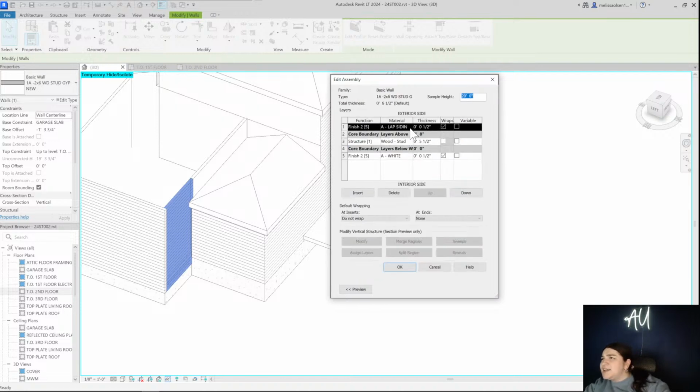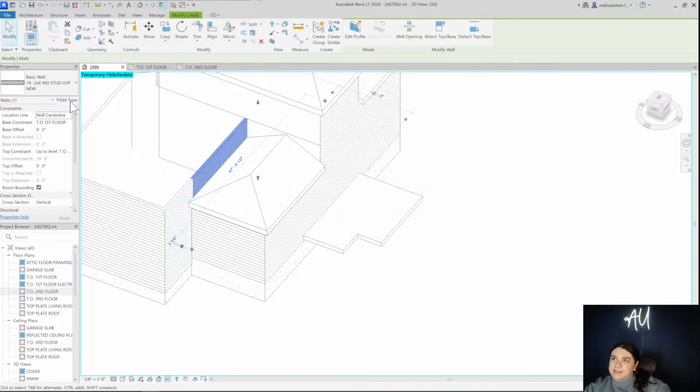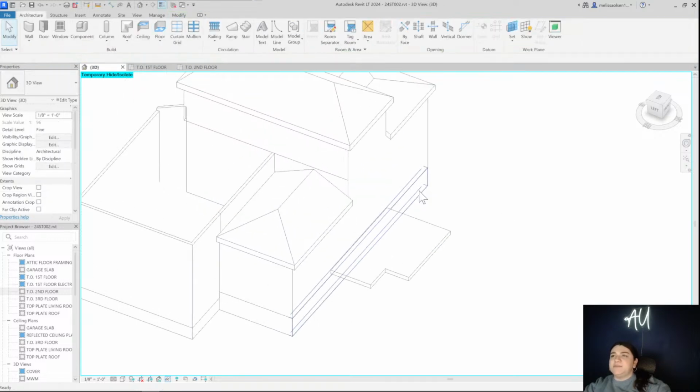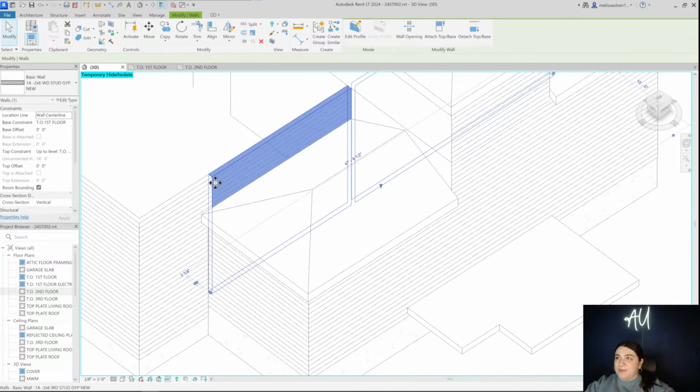So this is set to lap siding. I'm going into this. This is also set to lap siding, so I must have painted it. I'm going to go into the Modify tab and remove paint. Yep, I painted it. So that's why the pattern wasn't showing up.